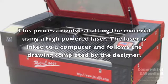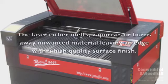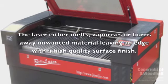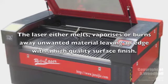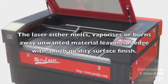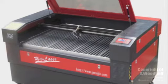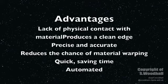The laser is linked to a computer and follows a drawing line produced by the designer. The laser either melts, vaporizes, or burns away the unwanted parts of the material, leaving an edge with a high-quality surface finish. This process is ideal for manufacturing signs from acrylic sheets. The advantage of this process